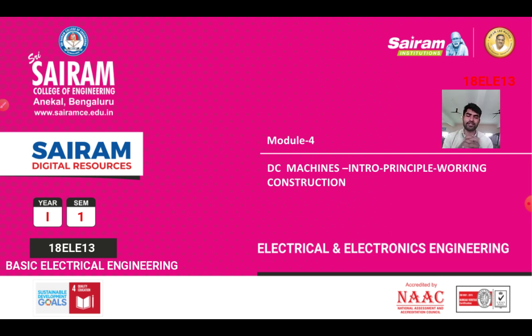We discussed it in the third module, right? The transformer is the best example for statically induced EMF. Conductors are stationary, and the magnetic field changes from primary to secondary. That is flux linkage between primary and secondary. That is statically induced EMF. Here, in the motor or generator, it is dynamically induced EMF, because movement and motion will be there. So in dynamically induced EMF, the conductor is rotating and the magnetic field is stationary or constant.